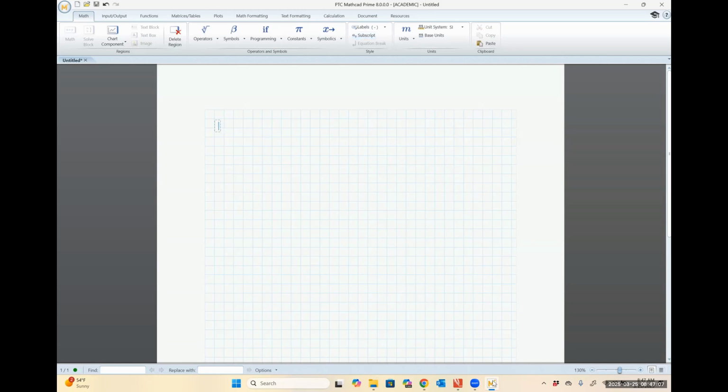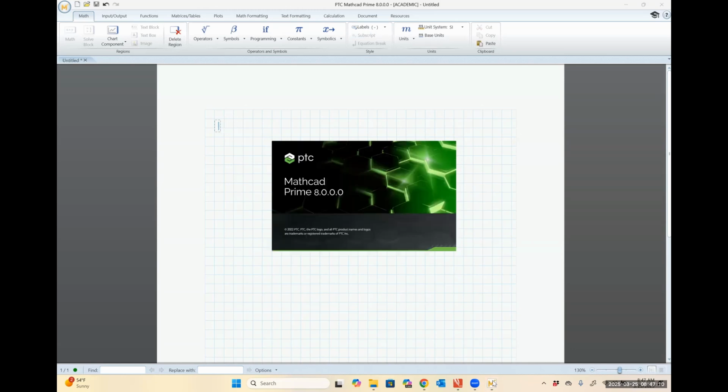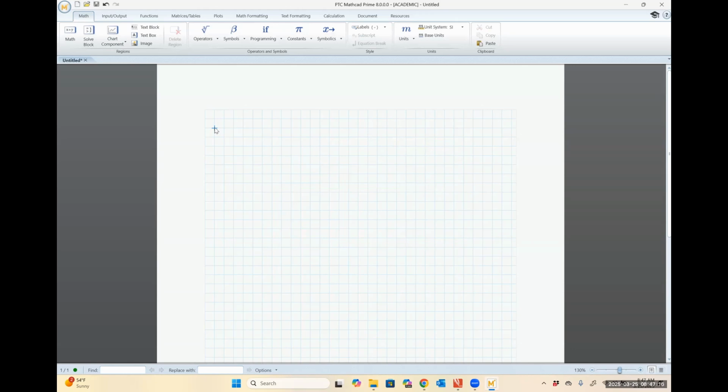Let me go through this slowly just in case you're not familiar with MathCAD. Sorry, I don't know why it looks like it's opening another version of it. So capital V, that's fairly obvious where I got that from. If I press Control and then minus, that allows me to do subscripts. So I'm going to have AB, and then I'm going to press Shift and colon, and that gives me this colon equal sign. This is how I give variables a value. I'm going to do 120. So open parentheses, 120.